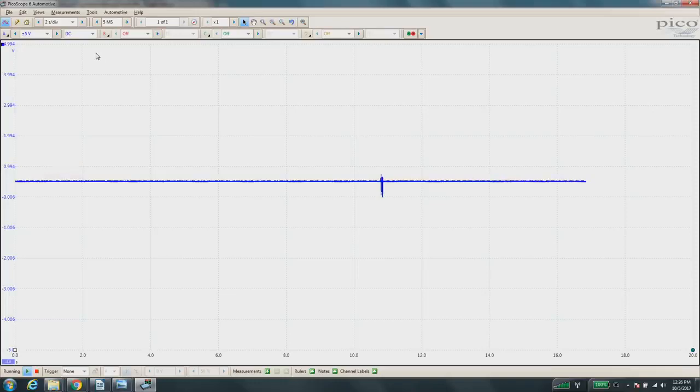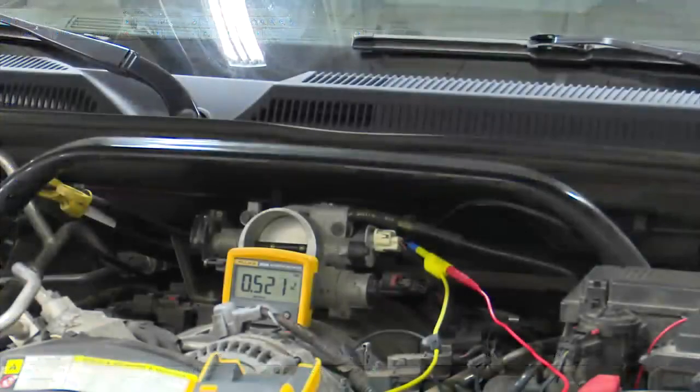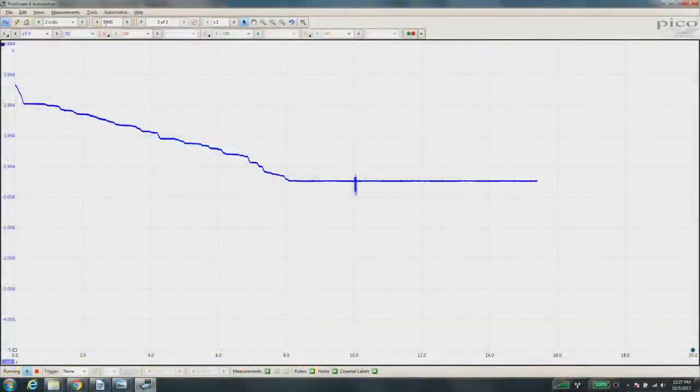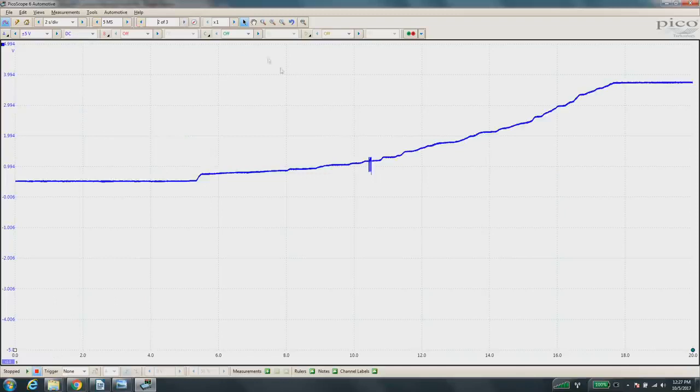All right, so we're going to start with the meter over here. And what I'm going to have Jim do is slowly cycle through the 0 to 100%. Go ahead. And obviously we should see our meter changing as we go through it. This would just be considered a sweep test, right? And wide open should be somewhere right about there, and then we start going back. All right, beautiful. And what that looked like on the scope was a nice and slow path. Exactly what you guys would probably expect to see, right?